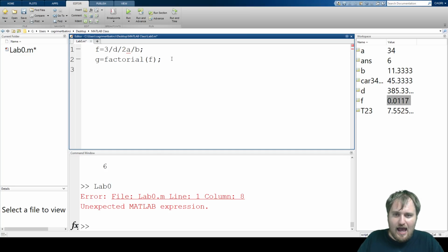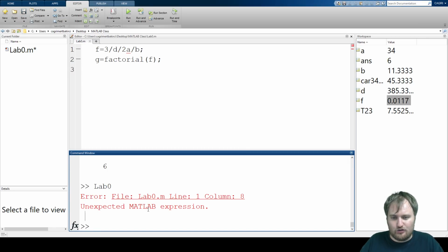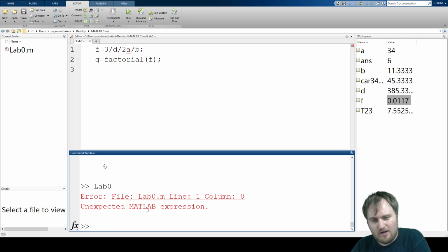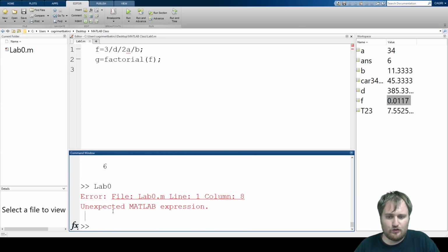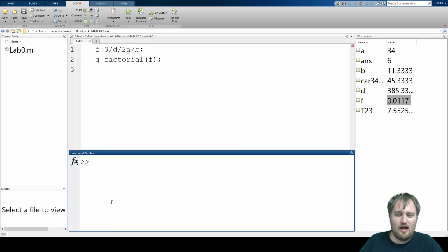That's great. And now, you can keep writing code. So also, another way to use the command window, you can run quick codes. Like if you want to see how crowded this command window is, I want to get rid of those things. I want to clear it out. You can write clc. That's a command that you will just learn in time. And now you just learned that clc clears the command window. There you go. Now there's nothing.